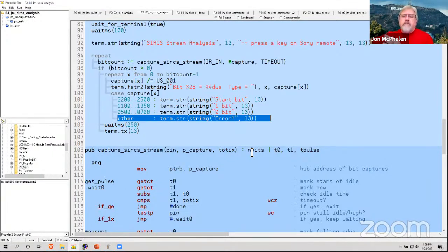All of them on this multi-drop bus will see the command, but they would only respond if their address matched. That protocol was carried over in the IR remotes as well. This is what allows a multi-function remote to operate, because the same commands can go to different addresses, and we can select that by, for example, on this remote, there's a button here that says TV video. So that selects the mode.